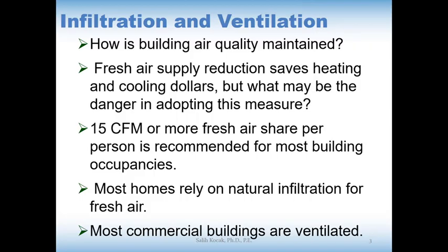So infiltration occurs, we cannot prevent it, through the openings under the doors, next to windows, and when we just open the doors, or again some cracks, maybe in the sides of the walls. So these are going to provide the natural infiltration. In the case of a roof, an attic or crawl space, they are all going to add to this natural infiltration.